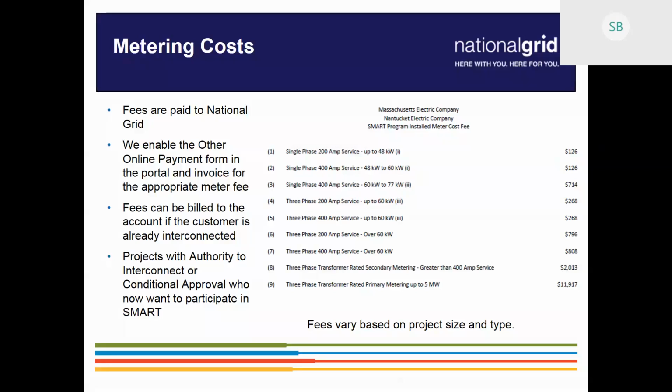We just know the total that's been generated or consumed between one day to the next. But if it's an interval meter, under the enhanced metering tariff, we do offer additional pulses to be provided, so we can install a KYZ cabinet and you can get the data from us. But there will be additional charges for that.